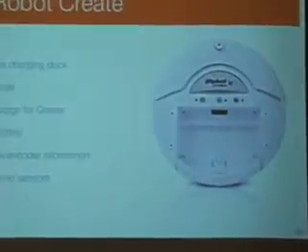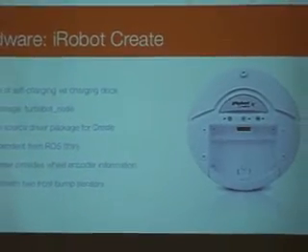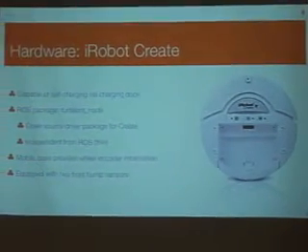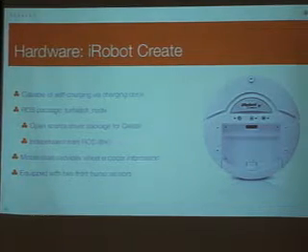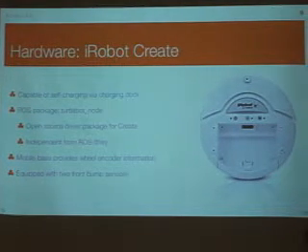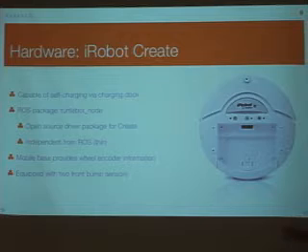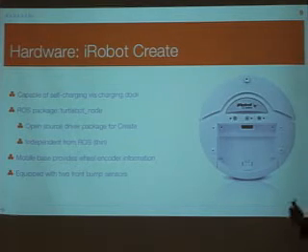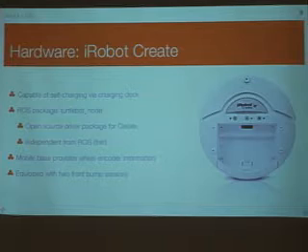This iRobot Create was a hobbyist robot designed explicitly for robotics development, and it integrates into ROS using an open source package that is thin and therefore independent from ROS. So the code that we created for this project could be used for another platform as long as it has another thin driver. The two important parts of the iRobot Create are the wheel encoders, which are a little inaccurate, so I'll talk more about that later, and the front bump sensors, which we programmed in our forward navigation to make sure it stops in cases of collision.